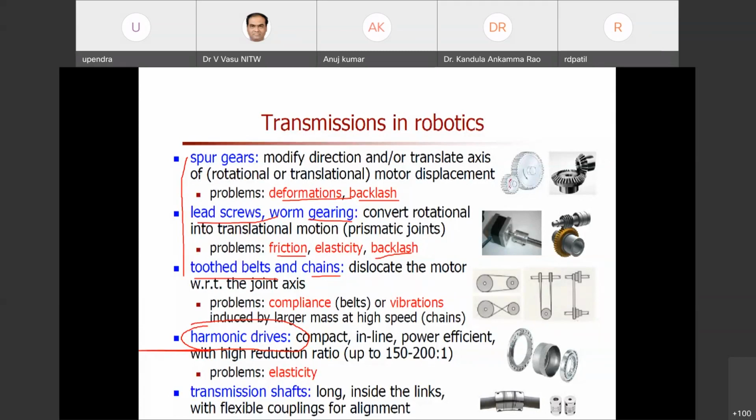Okay, so backlash error means, suppose a gear has one tooth here and a tooth of another gear is there like this. Okay, if wear occurs between these teeth, we get a gap. This is one tooth of one gear, and another tooth of the other gear comes and matches like this. Okay, if you get wear, the teeth will have a gap. Because of this, we get a backlash error and lose accurate position.